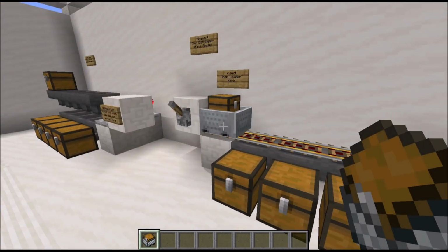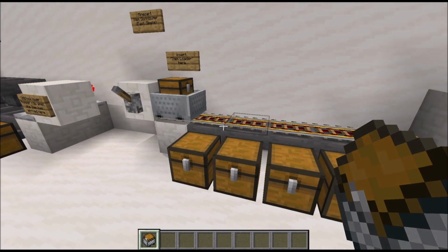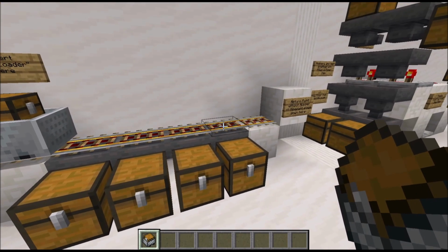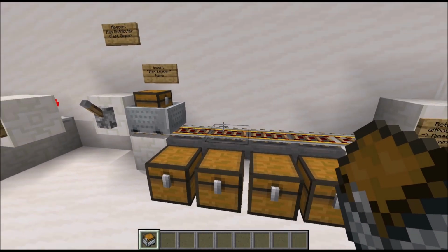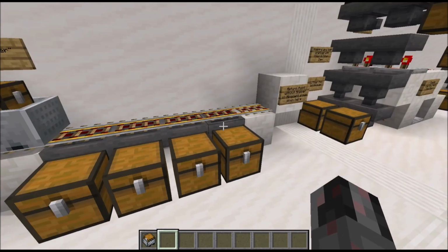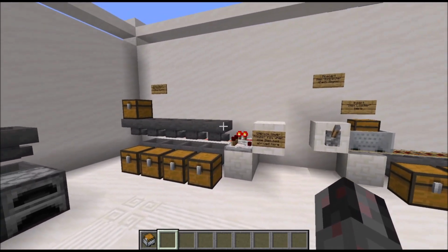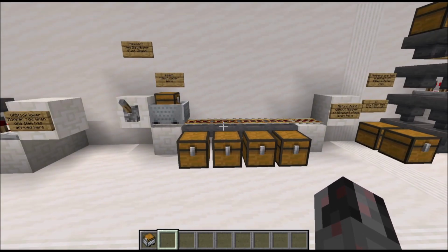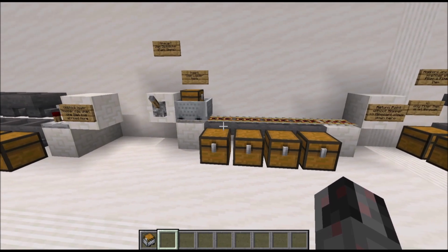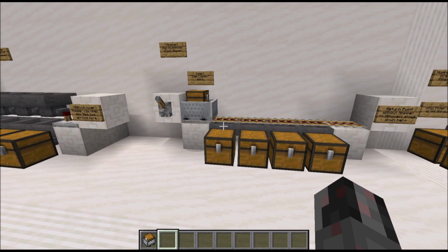Because this is going back and forth, you have a situation where you get 2 items in here rather fast and 2 items in here rather fast, but in the middle you get 1 item, then a short pause, then another item, then a short pause, and so on and so on. So the item distribution is not nicely automatic or somewhat robotic like in this situation here, but you have this back and forth situation. This is one possible issue if you try to activate your modules here through the items flowing into it.